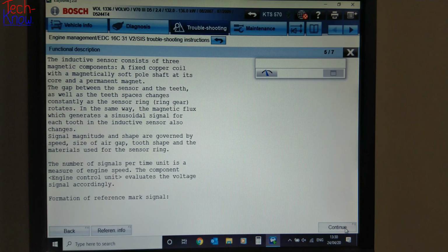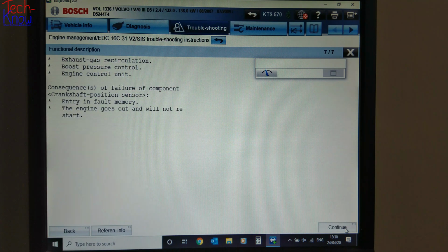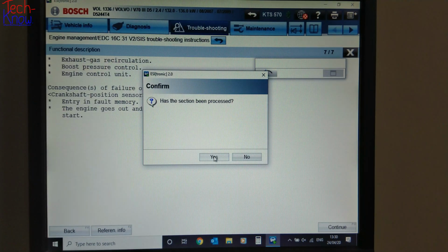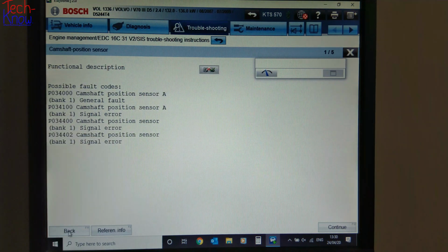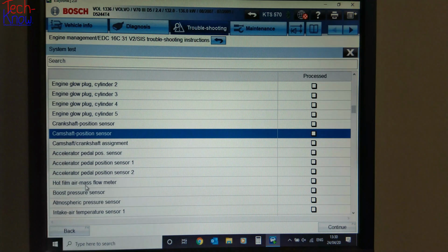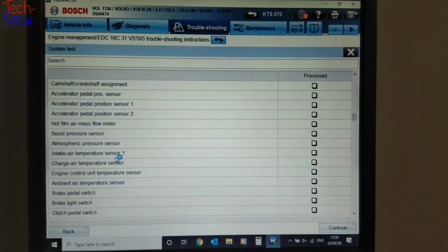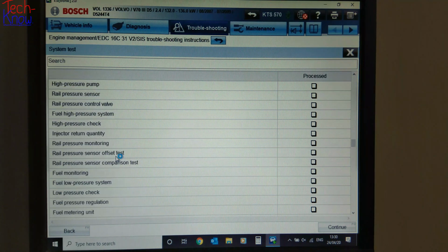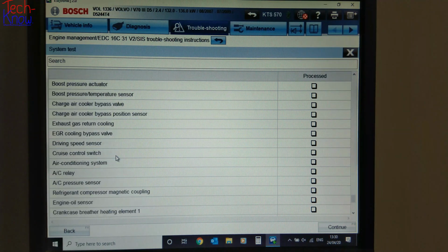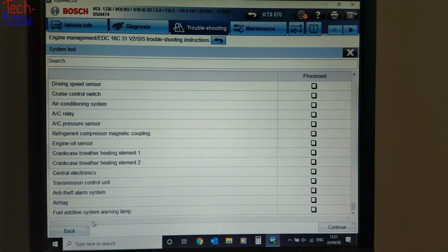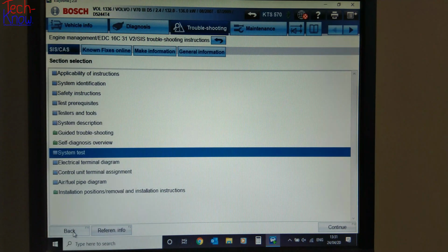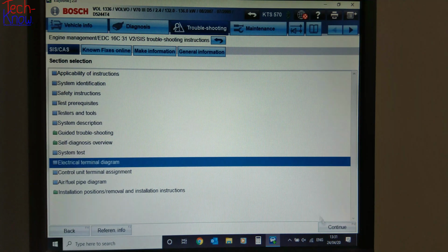Without teaching grandmothers too much, here's our standard wiring diagram. I'm sure you're familiar with this type of wiring diagram showing various components. To move to the next page, we just make it smaller again and click Menu. Again, we can look at the key and the individual wiring diagram showing us where various components are and how they are wired to the ECU, which is through the middle here. Generally, your positives are at the top, terminal 30 and terminal 15, and your ground, terminal 31, is at the bottom. You've got your reference points here, and certain of these component boxes will refer to that component back at terminal or position 13. That connects back to 13, which would be on the previous page.